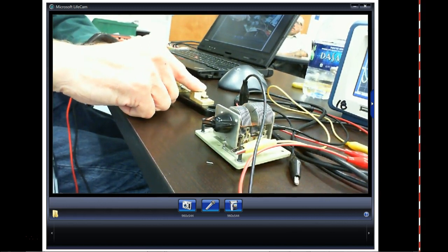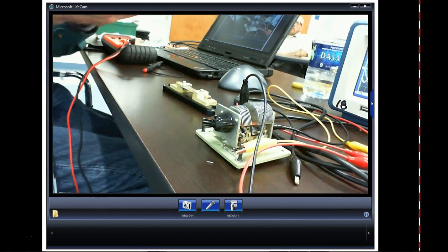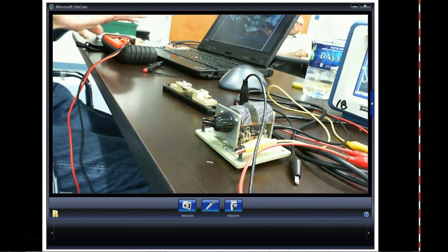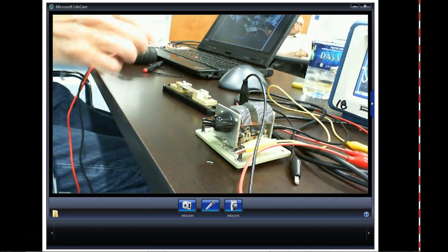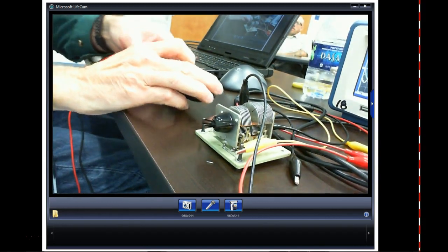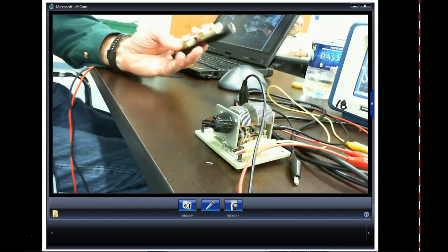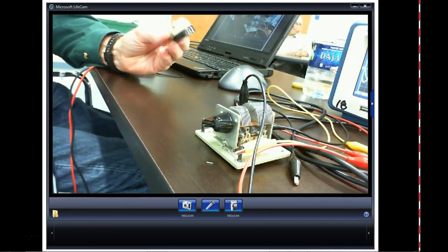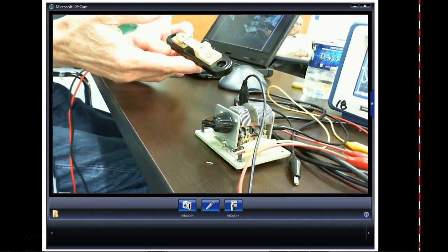Understand that? So 1 millivolt means it would be 1 amp. So this is the way the amp meter works. If I was to take these meters apart, you would see these current shunts, which is basically nothing but a piece of wire. How much resistance would that be? 50 millivolts or 50 amps? Way down in the milliohms, right? You understand that? So this is the current shunt.